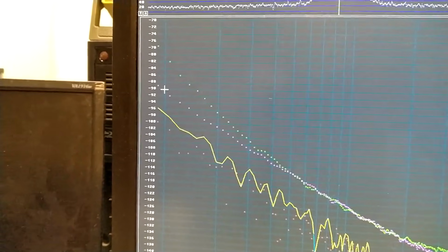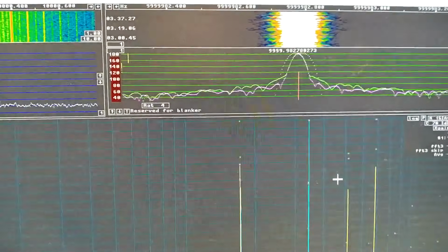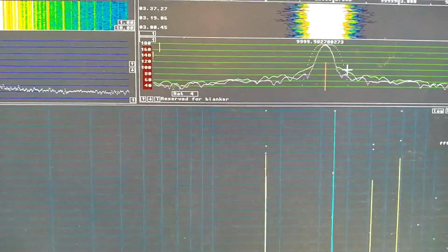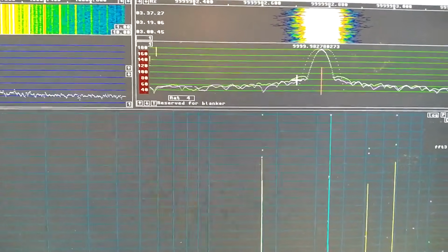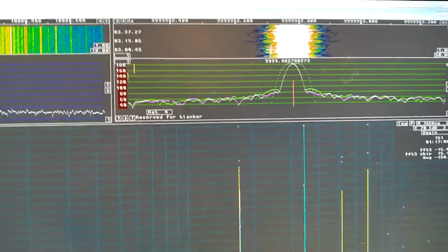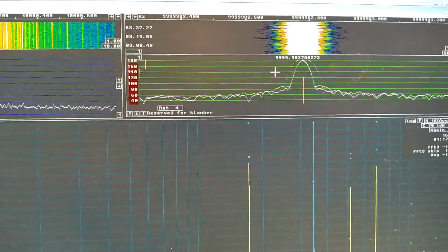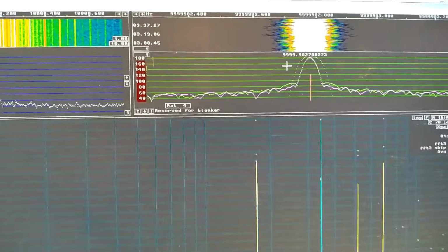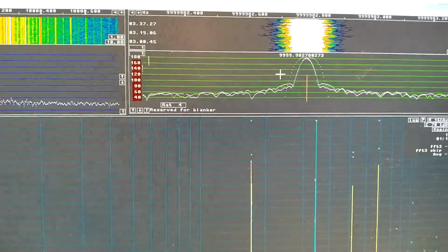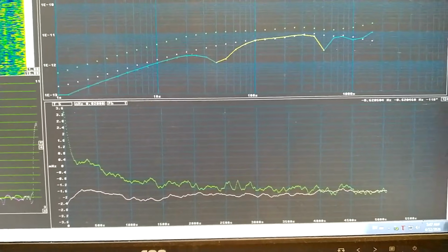That is 12 decibels. And that is easily seen here in the spectrum. This is about 10 decibels. And it's always stronger. And you can see also in the waterfall. So there is something which is not so good with the channel 1 oscillator at very short distances to the carrier. And here is frequency versus time.